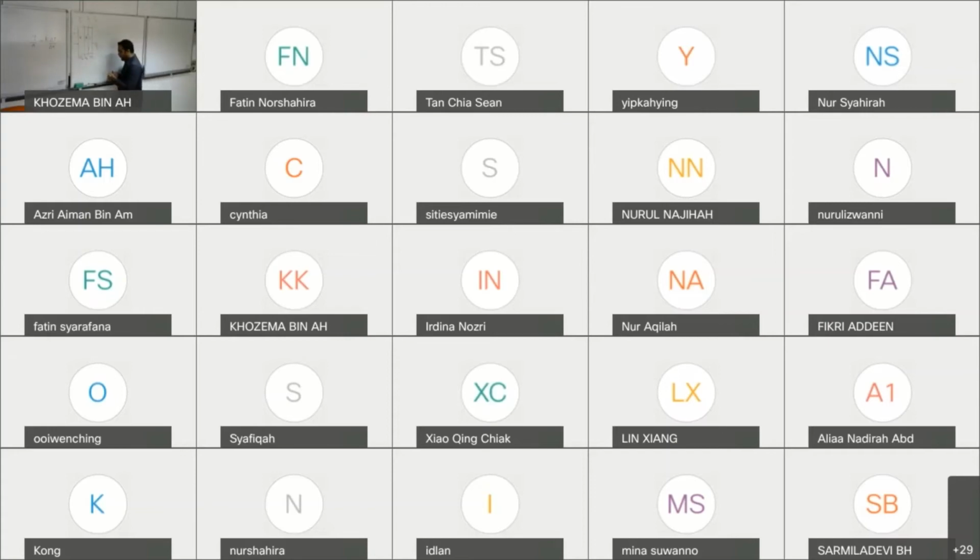If you look at the equation just now, I said that Q over A is equal to delta T overall over R overall. Delta T overall will be T1 minus T4. And R overall is equal to RA plus RB plus RC.